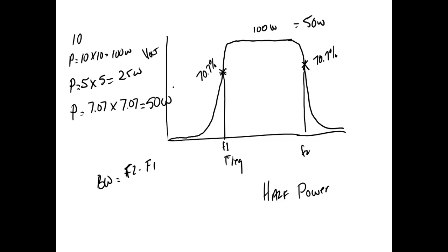So if I was going to measure it with my oscilloscope, I'd get me a function generator. I would put it across my media. I'd start at 0 hertz, and I would go up until it builds up to a maximum, right? You understand? And then I'd measure F1. I would start dropping it down to 70.7% of the maximum. I'd keep increasing my frequency until it dropped down to 70.7%, and that would be F2. Now we have formulas to calculate what we expect the bandwidth to be.